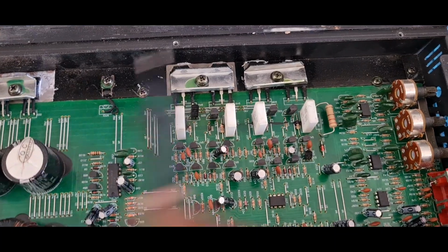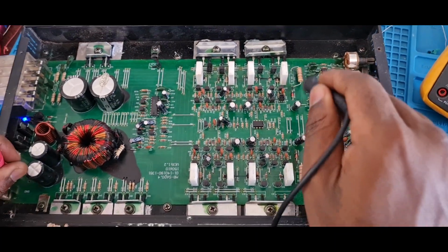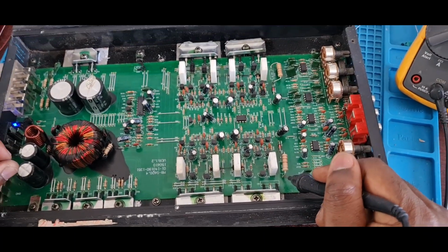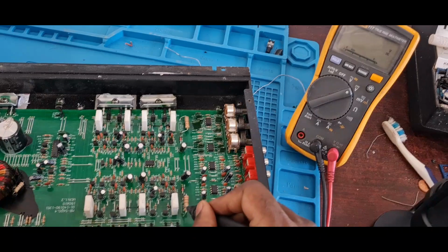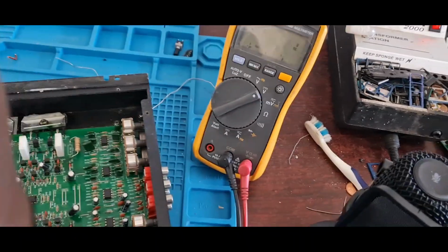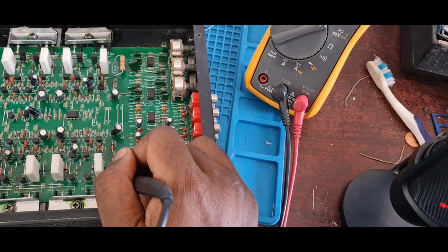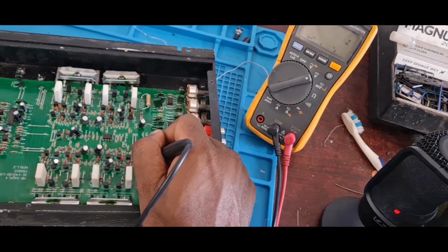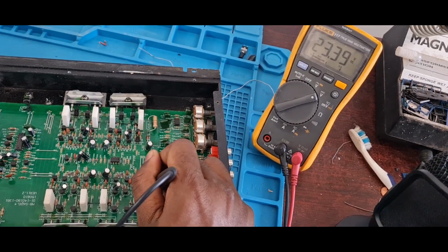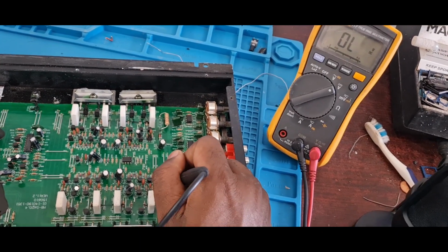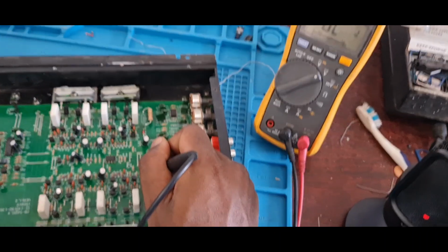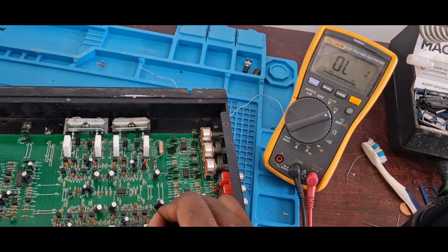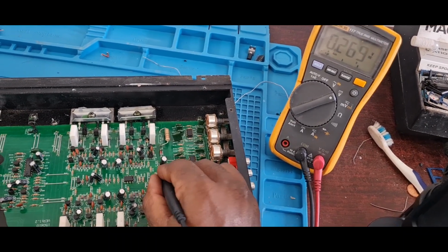So what I will do is take out the motherboard, and then start taking out this resistor and the diode to check, because this gives me voltage on the two sides. This resistor here is a 2 watt resistor, and it gives me 27 volts. You can see I just changed the probe, so it's negative 27 volts, the same. And on the other side it gives me 23 volts. This is meant to break down the power, and this diode works together with it to get the right power. Of course the capacitor as well keeps the storage voltage.